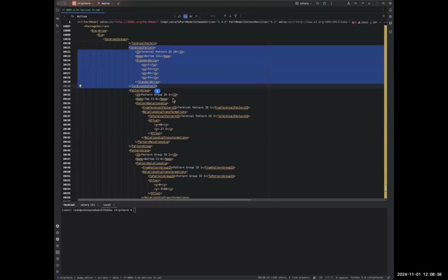The NX, NY, DX, DY for each terminal pattern is set to describe that group. But if we went terminal by terminal through the whole bump map, in the X direction it would be half of 96, and in the Y direction half of 55. So my point is that every single terminal follows that pattern. So you could use the location.